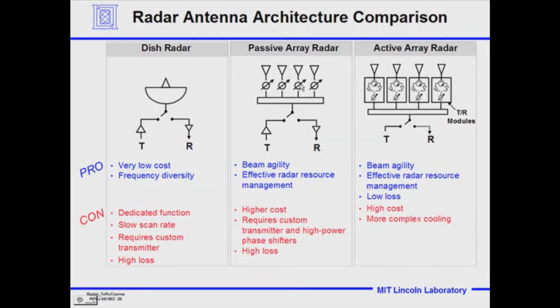So we could track a target over 45 degrees in one direction, and then microseconds later send a burst of energy over 30 degrees in another direction. I mean, if we have a phased array like that PAVE PAWS radar that has elements in both vertical and horizontal dimensions, over a very wide angle, say plus or minus 45 degrees, we could send beams out in every which direction, every tens of microseconds being the time to change the antenna's pointing. Of course, it's going to take time for the pulse repetition rate.